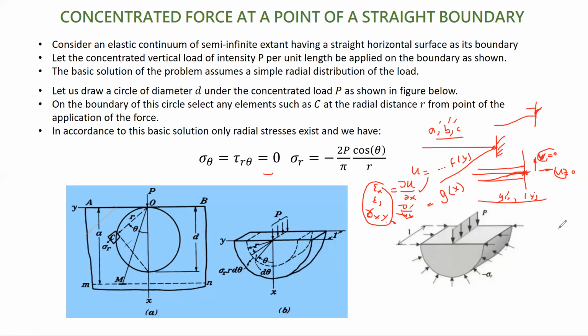That is to say, if I have a disk and I calculate stress for theta equal to 0, at that point, when I turn 360 and I put in my equation 360 degrees for theta, I should not get a new value. I should not have multi-value, infinite number value for the same point on the object. These are boundary conditions. That is, in a sense, what I would like you to remember and learn.